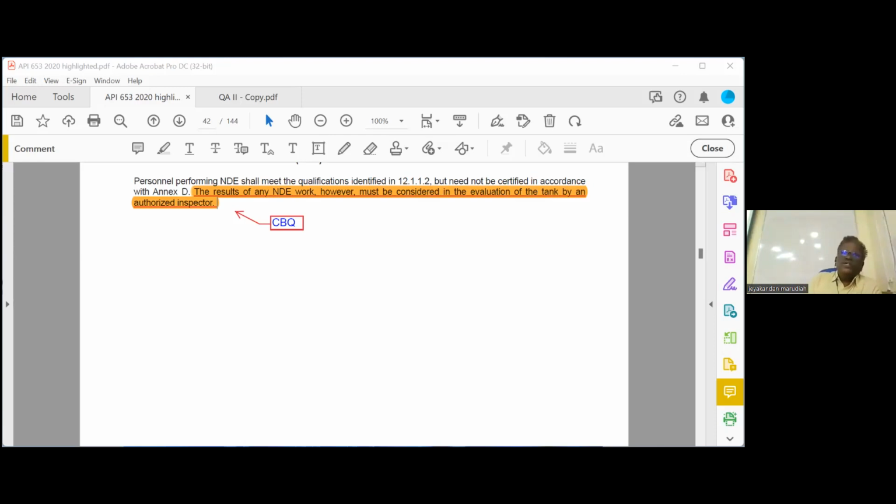You can use robotic UT thickness measurement. When the tank is filled with oil, we can send the robot inside by remote operation. Yes, you mentioned that, but is there any specific time that I need to unfill the product from the tank? When the tank is severely leaking, we have to unfill. That's all.